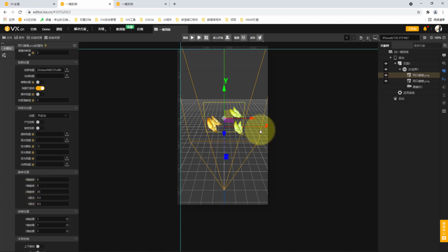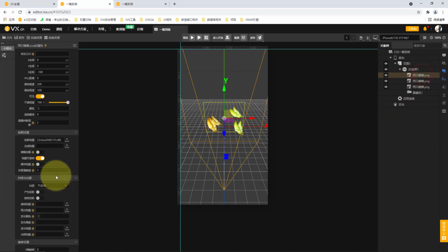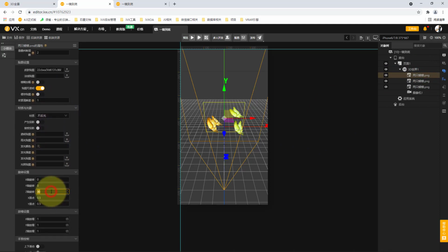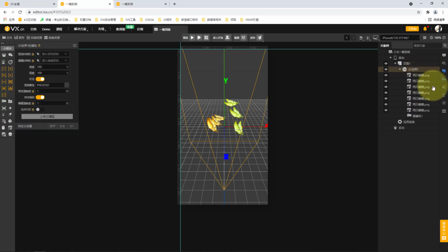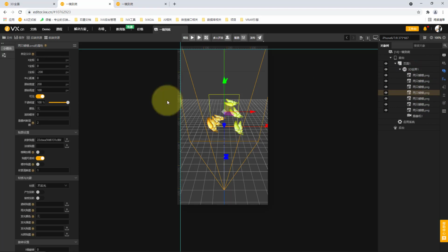It has set the origin as the center by default. We can take a look. Which axis do we want it to rotate around? If it's the y-axis, how does it rotate? Is it like our mobile phone rotating left and right? Similarly, if we rotate the x-axis, is it a folding effect up and down? So what are we going to rotate in the end? It's our z-axis that rotates. Therefore, we select a z-axis rotation here, and we add a 30-degree rotation to it. We can see that it rotates 30 degrees around our z-axis, so that our second butterfly is ready.